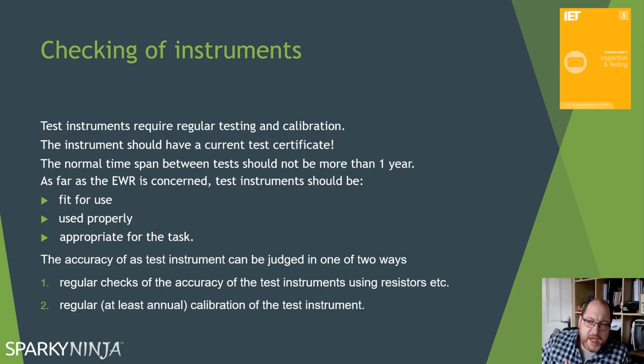Appropriate for the task, yeah. When we go to prove isolation, for example, we use a GS38 voltage indicator. We would not use a neon screwdriver type instrument. We also wouldn't use a multimeter when we should be using a multifunction tester for testing electrical installations. So make sure it's suitable for the job that you're asking of your instrument.